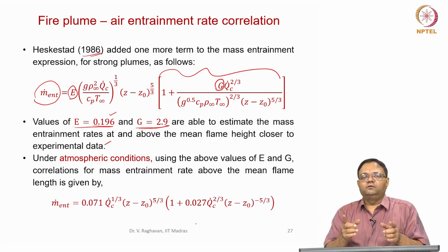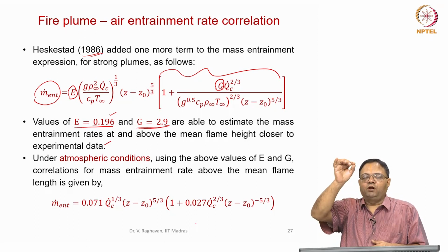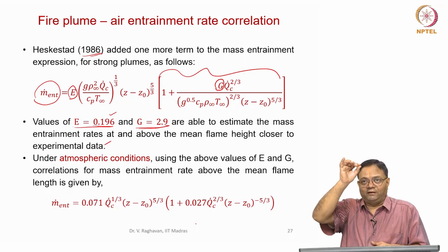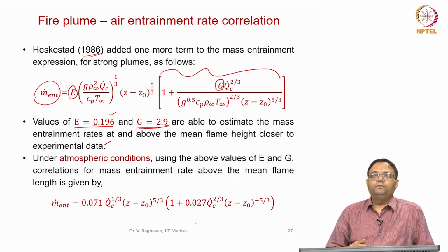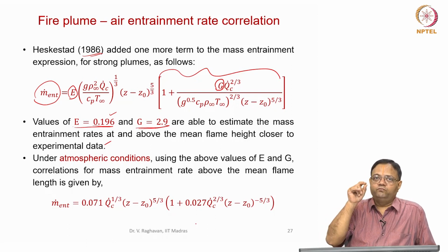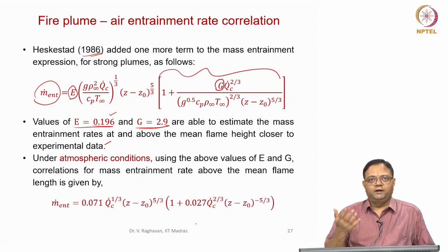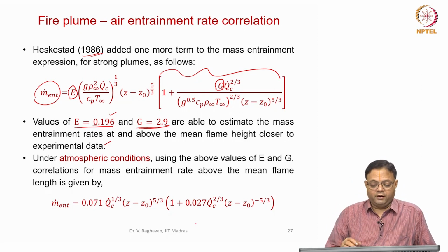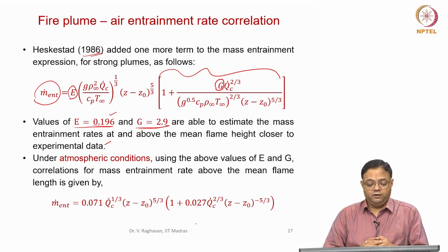The Gaussian profile says the center velocity will be maximum and it goes to 0 at the radius. You can do that, or you can say the radius at which the center temperature or center velocity drops to half of the value. So BT and BU can be taken. Then delta T variation also was seen.